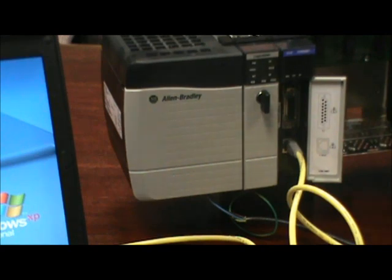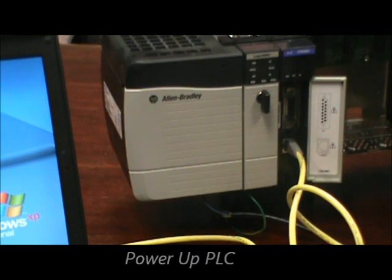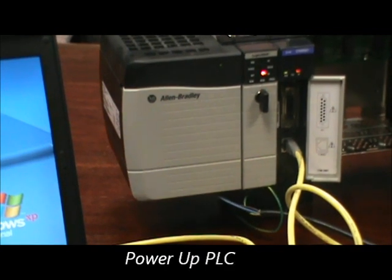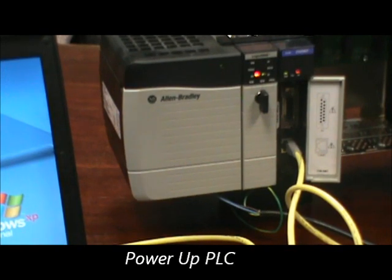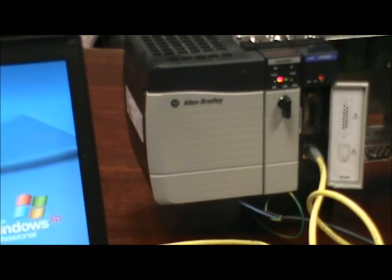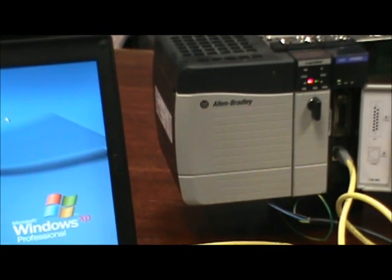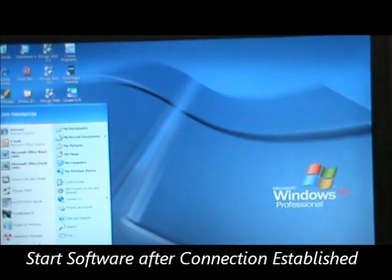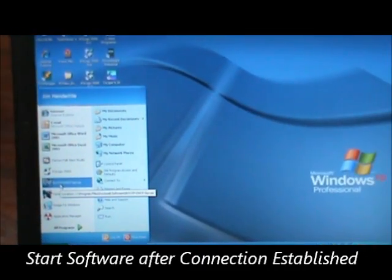At the beginning, before you use the BOOTP software, power up your PLC rack. It will take a little bit of time before the PLC recognizes the PC internet connection. Once the connection's been established, then it's okay to start the BOOTP server. We're starting.